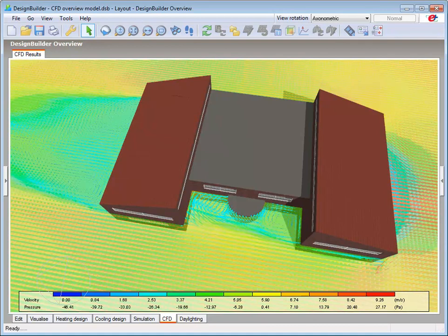Another important initial concept for CFD analyses is that of boundary conditions. These can be specified in a number of ways and are essentially fixed constraints on the calculation input by the user. For example, surface temperatures and supply air temperatures and flow rates are specified as starting conditions for internal CFD calculations. In Designbuilder, the specification of boundary conditions for external analyses is relatively straightforward and just requires setting the building exposure, wind velocity and wind direction, and this is done using a single dialog box.